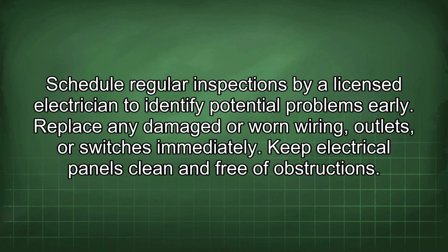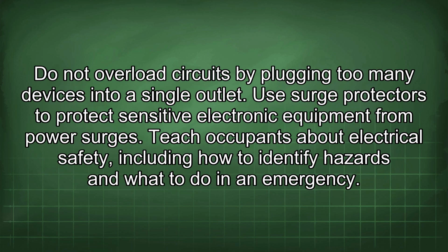Schedule regular inspections by a licensed electrician to identify potential problems early. Replace any damaged or worn wiring, outlets, or switches immediately. Keep electrical panels clean and free of obstructions. Do not overload circuits by plugging too many devices into a single outlet. Use surge protectors to protect sensitive electronic equipment from power surges.